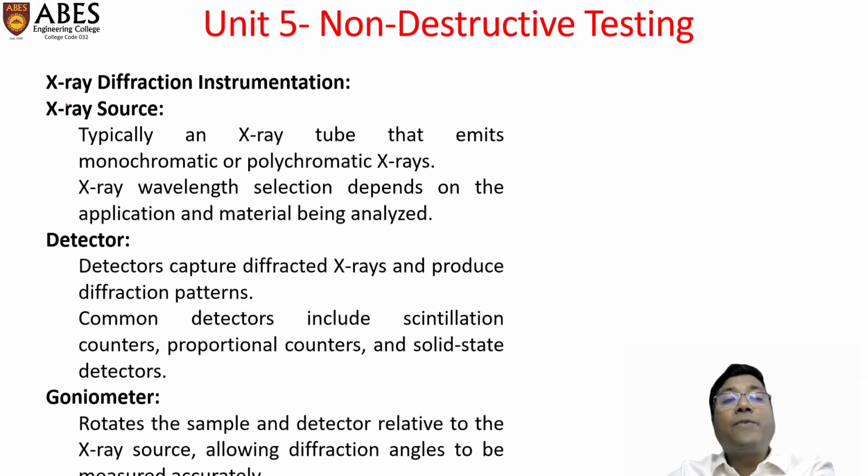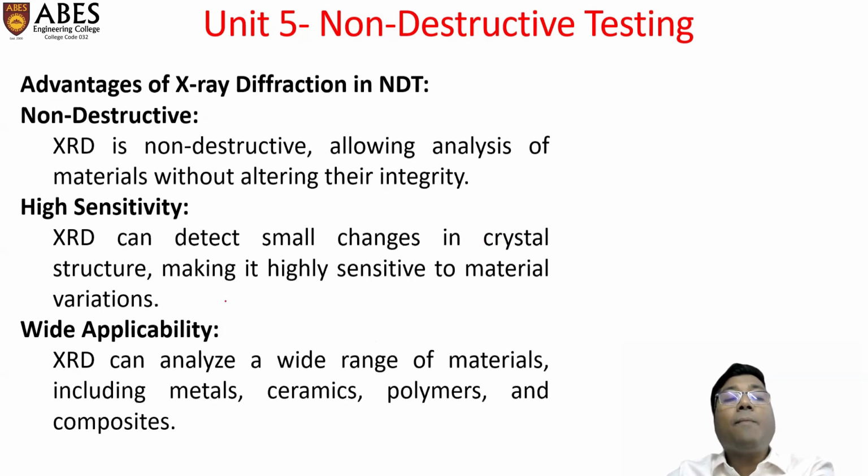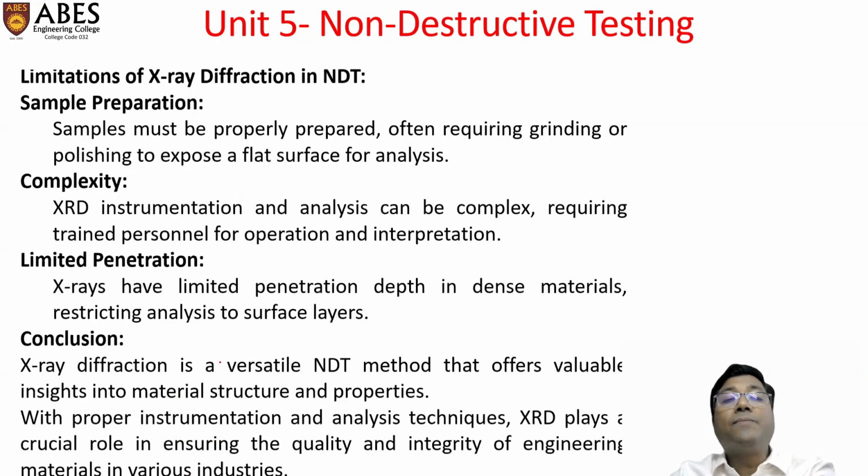The instrumentation used for X-ray diffraction is the X-ray source, which is important, the detector, and also the goniometer. Advantages of X-ray diffraction in NDT: it is non-destructive, allowing analysis of materials without altering their integrity. High sensitivity: XRD can detect small changes in crystal structure, making it highly sensitive to material variation. And also wide applicability: it can analyze a wide range of materials including metals, ceramics, polymers, and composites.